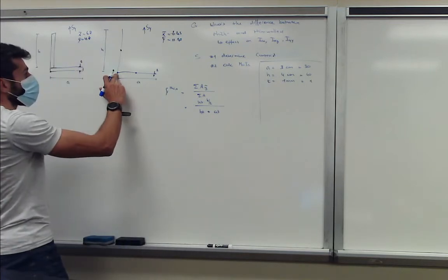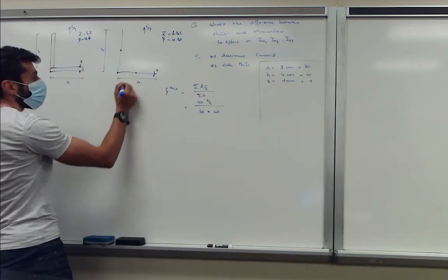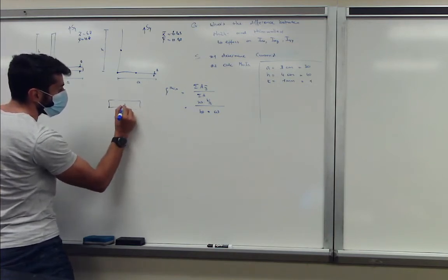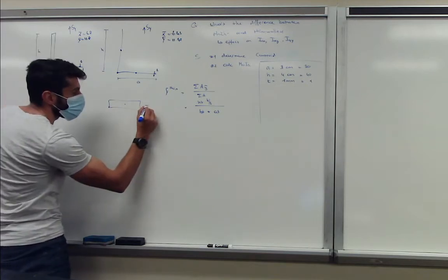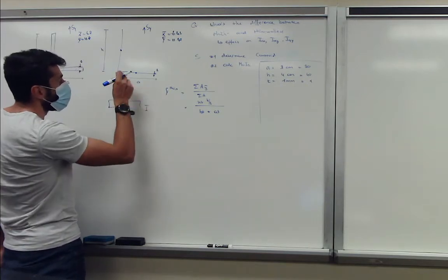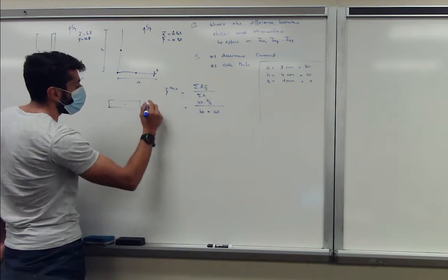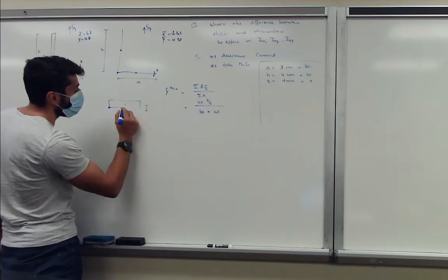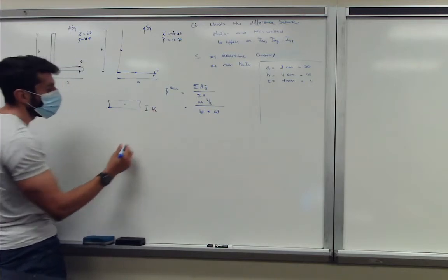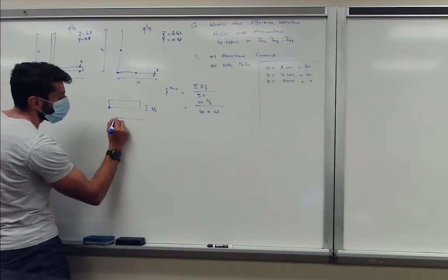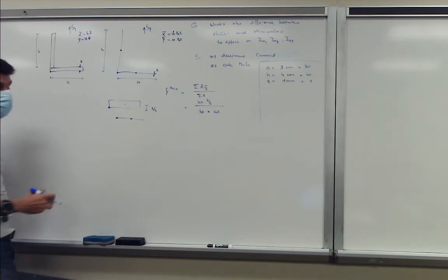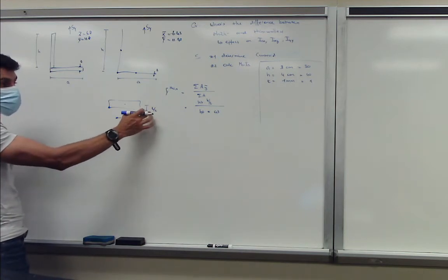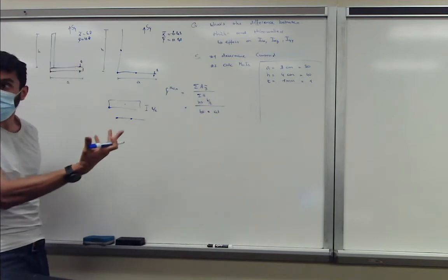Because this location and so the height with respect, if we zoom out for this one, we had our reference point here, and this was our local centroid. So the distance between our horizontal flange, width flange, and this reference point here at the bottom left, that will be T over 2. But in the case of a thin weld, you assume it's basically 0 thickness, so these two coincide. And therefore, this arm that you normally have is basically 0, and that drops out.